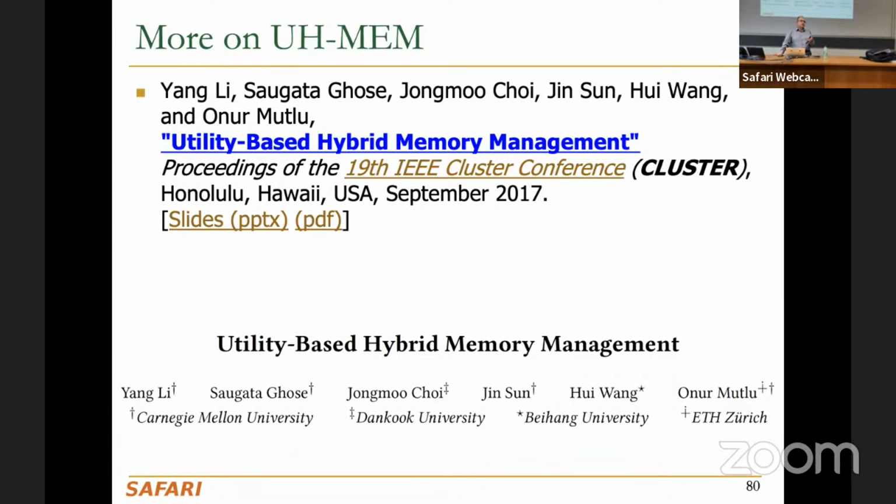No, so the thing is that when you have a miss in row buffer, you need to read again. You need to sense a PCM row, right? And you need to pay for PCM access latency. But when you have a row hit, you just need to pay for kind of an SRAM access latency, right? Because the row buffer is essentially SRAM memory kind of thing, right?